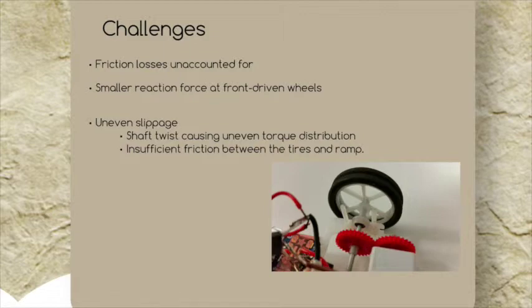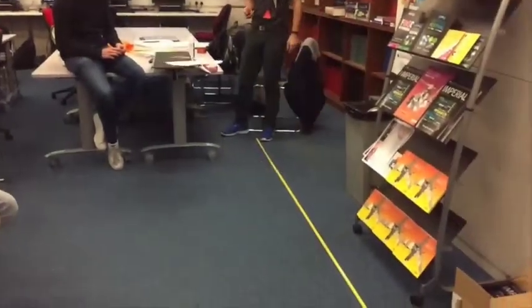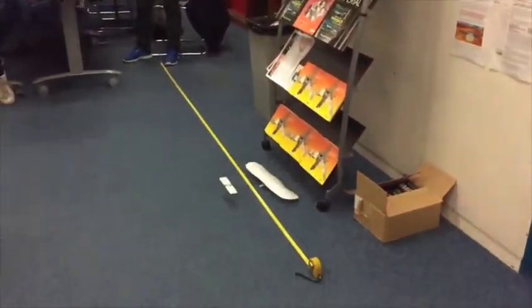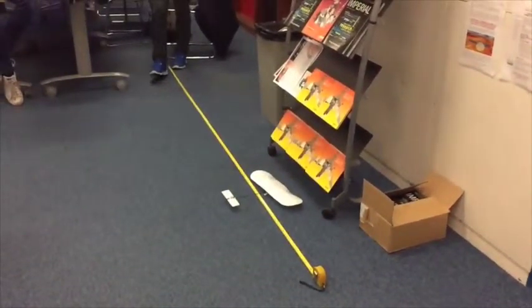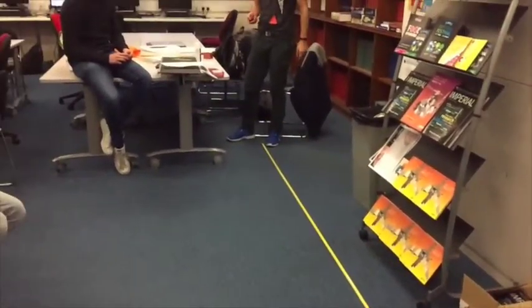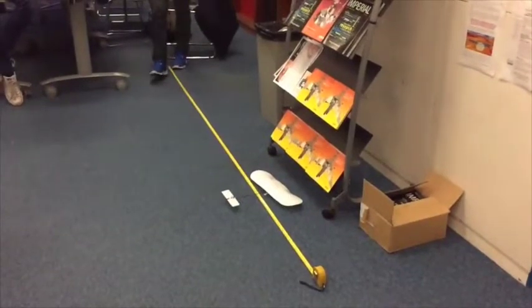During the gliding phase, the glider was very susceptible to roll perturbations, which would cause it to deviate sideways. We tried adding dihedral, but it was relatively ineffective. To solve this issue, the roll angle as well as the setting angle of the adjustable horizontal tail was set such that the rolling and yawing moments produced balanced the laterally unstable glider.